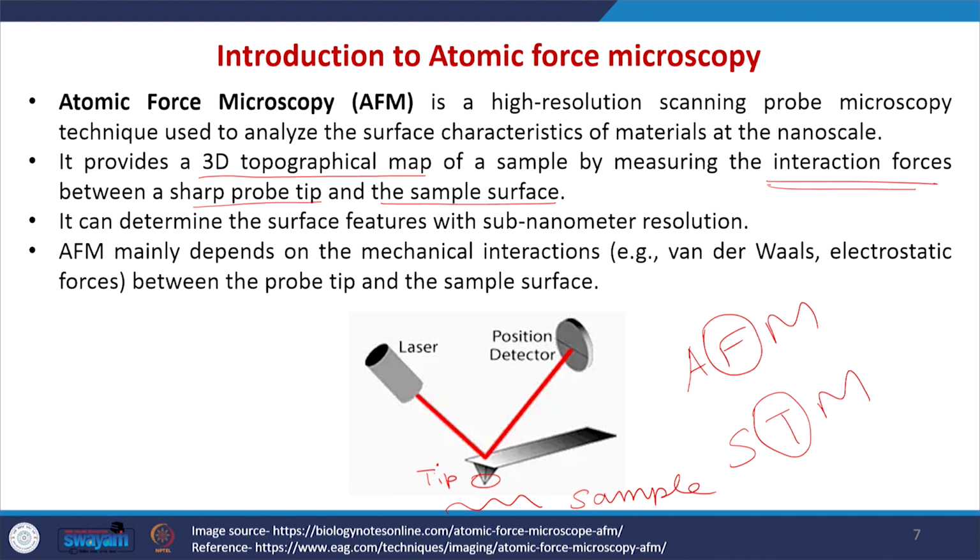This AFM can determine surface features with sub-nanometer resolution. That is the advantage of this AFM, and it mainly depends on mechanical interaction. As I told earlier, it mainly depends on mechanical interaction such as van der Waals or electrostatic forces between the probe tip and the sample surface. Let us see the parts of AFM.